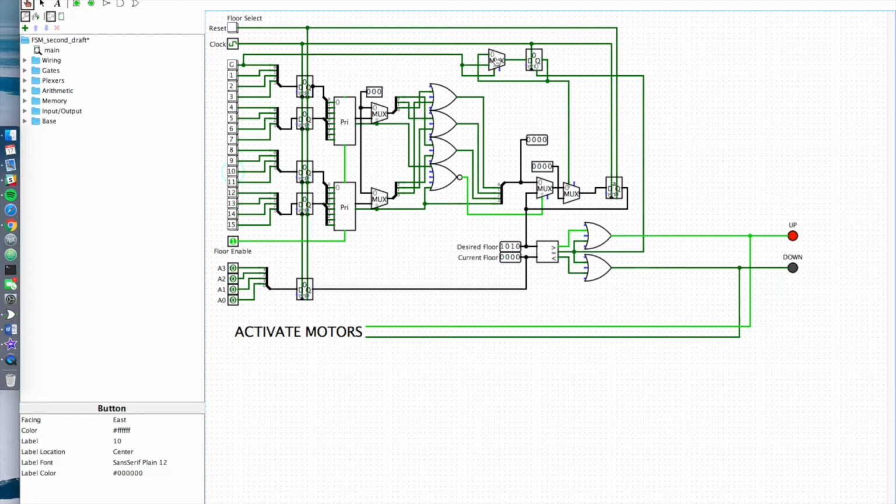The reason for using this multiplexer here is once you have activated this, if you let go of the ground button, then this select goes to 0, which means that you'll be selecting the top channel instead of the bottom channel. And you don't want the top channel to go to 0 once you stop pressing the ground button, so we latch the output of the register using this multiplexer. So this FSM completely encapsulates all of the requirements for the FSM elevator, and so yeah, that's that.